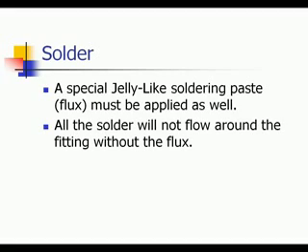One of the ways to connect metal is soldering. Solder requires very little heat to flow, usually less than 800 degrees. 95.5 solder is 95% tin, 5% alloy. All copper pipe fittings that are to be soldered must be cleaned with a sand cloth and/or brushes. In other words, they have to be clean.